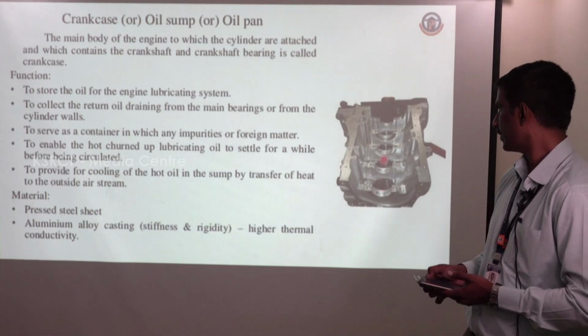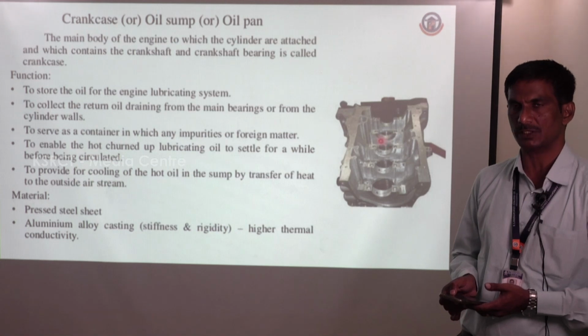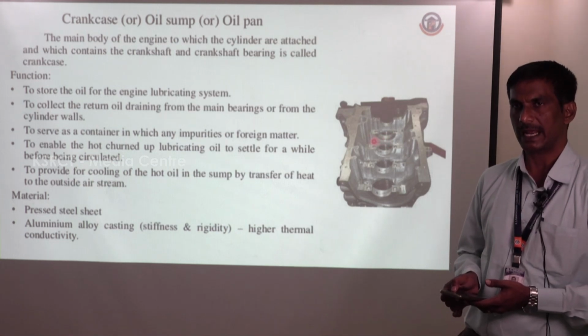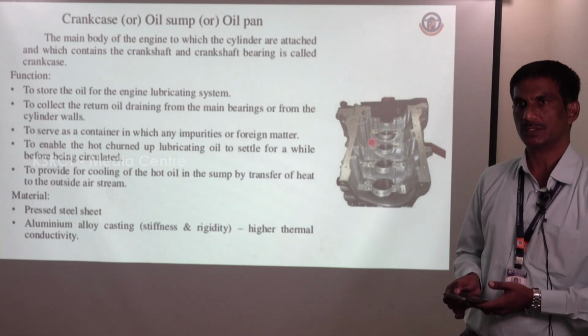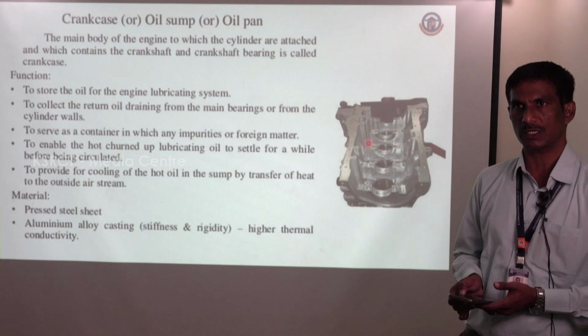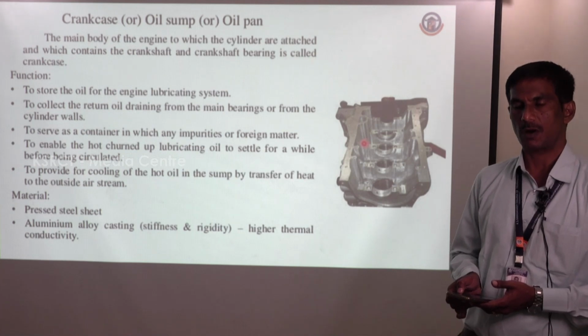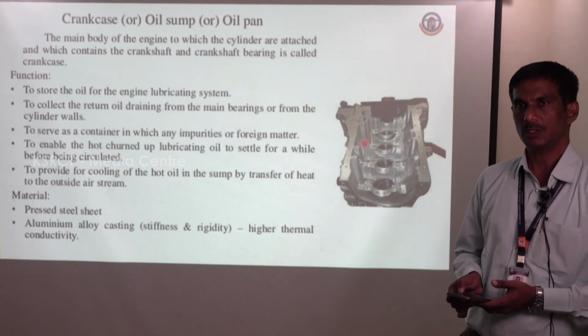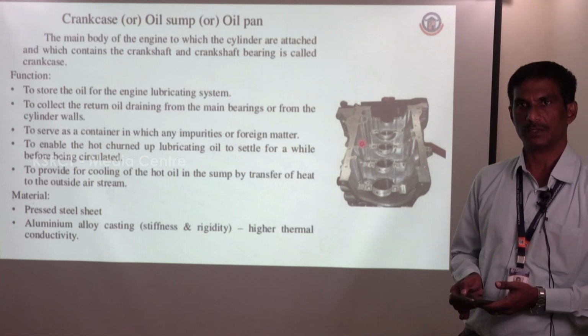Another thing, if the oil has any dust particles, they are also sedimented in the crankcase, and you can also drain the oil from the crankcase. So you know why we are using the lubrication oil. It is for lubrication in order to reduce the wear, and it also dissipates the heat from the engine components. So the crankcase holds the engine oil and also the crankshaft.